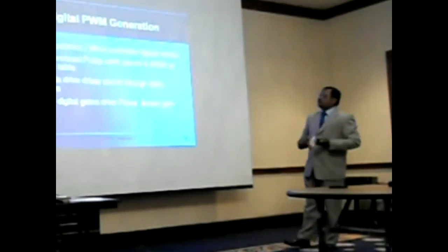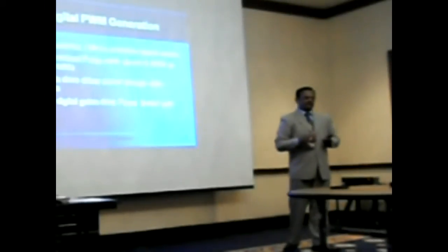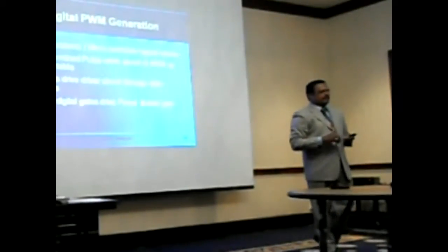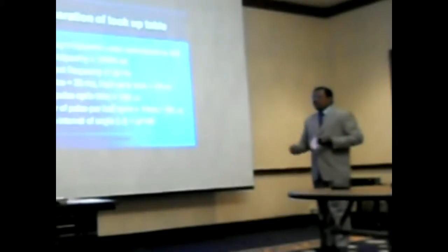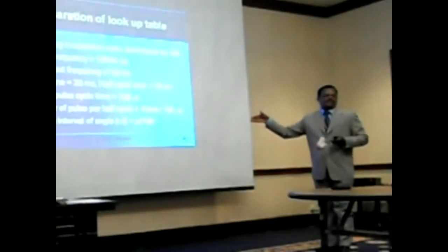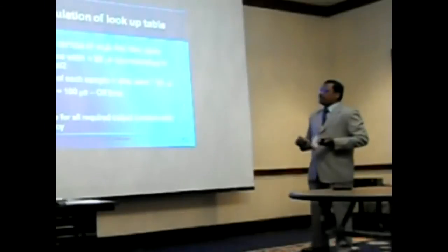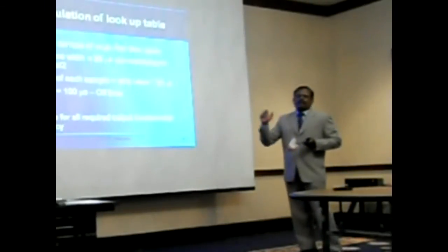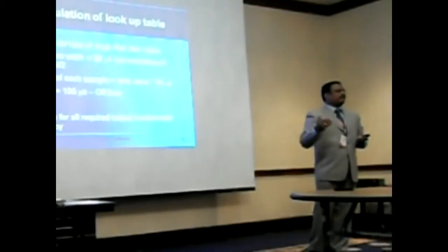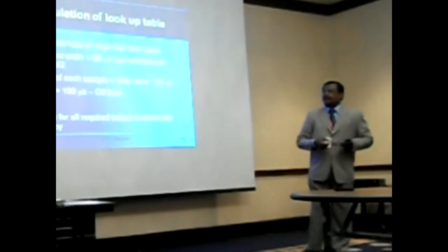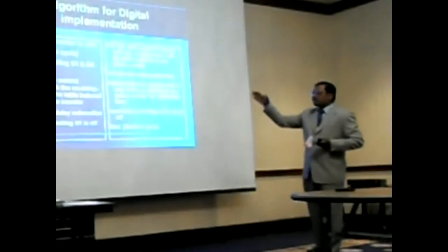And the generation methodology which I have proposed here uses a digital PWM technique, which is a software control. We can have a microprocessor or microcontroller based system. And for these systems, for 50 Hertz, the calculations are given here. Based on these calculations, the on time and off time of each sample is calculated, and these calculated on times and off times are stored in the memory, and each value is taken for each pulse, and the output pulse is generated by the output port of the microcontroller.